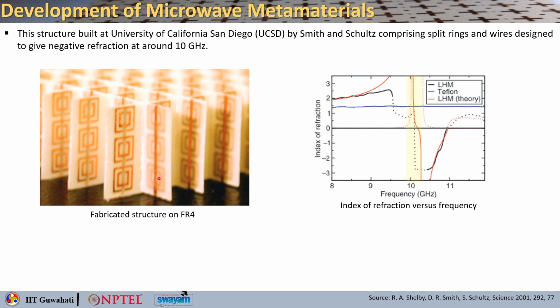On the back side there are these metallic wires, and then they have been assembled into an interlocking lattice to make this kind of structure. This was the actual calculation of negative refractive index. It shows that you are actually able to get negative refractive index for this left-handed material over 10 gigahertz. There are some asymptotes because of the limitation of the measurement equipment.